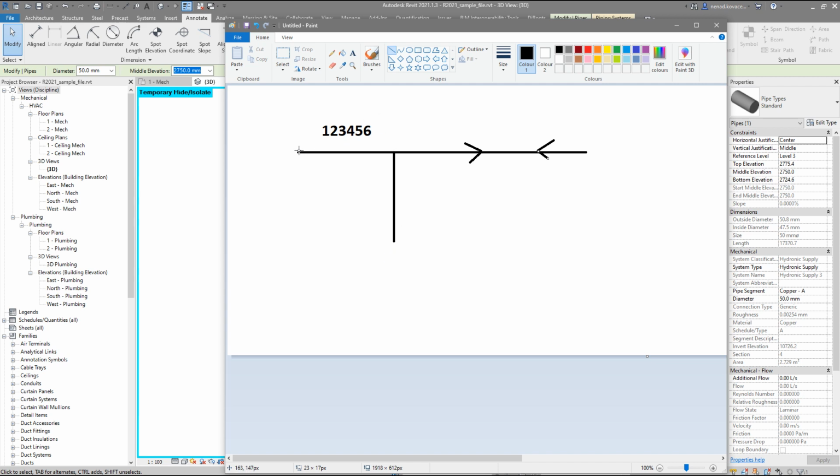Let's say we modeled from left to right: on the left part of this pipe, we will keep the previous ID which we already have. And then if we need to connect new pipes, we can continue to go from this left side. So again, over here we will have new IDs, but over here we will have the old ID, and then we can just repeat the command in order to tell Dynamo, I have some branch pipes over here, let's connect them with this ID.